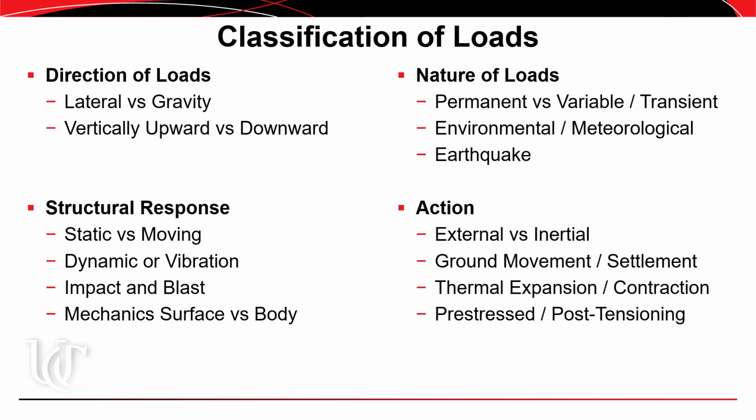And then the action that it creates on the building. It could be an external load or it could be an inertial force. It could be a ground movement or a settlement, thermal expansion, contraction. It could be pre-stressing or post-tensioning. And then lastly, there are also notional loads that we'll define later.